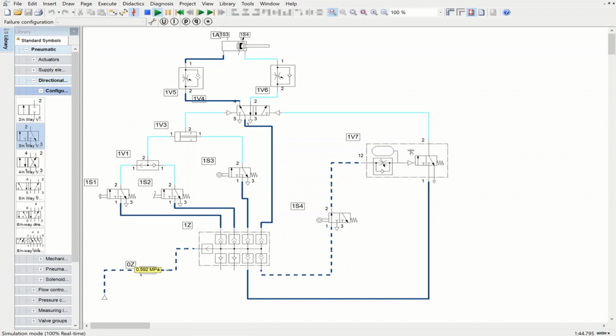You see we have a time delay, and then once the time delay has passed, it sends a signal here because this is going to shift to the second position, right? If you remember, the time delay valve will shift to the second position, the normally closed one, and it is going to be open. Air will pass from this side and get here, and this is going to be pneumatically actuated.